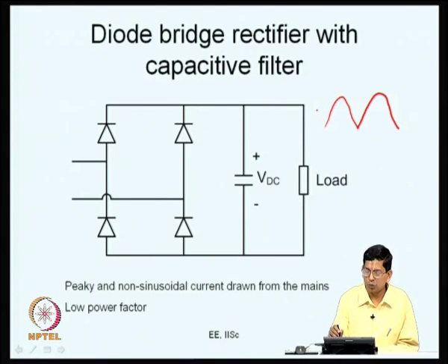It has a certain average voltage, but there is a lot of ripple. This is the average that you might want, but there is a lot of ripple on top of it. Such a high amount of ripple is unacceptable. So, the minimum filtering that you do is to put a capacitance here. Of course, there are additional filterings that you can do, let us say having an inductance here or an inductance here, but as I said, the minimum filtering that you do is a capacitance here.